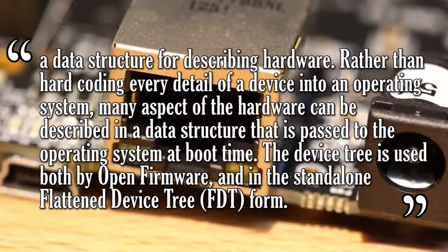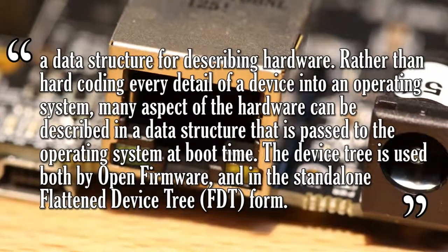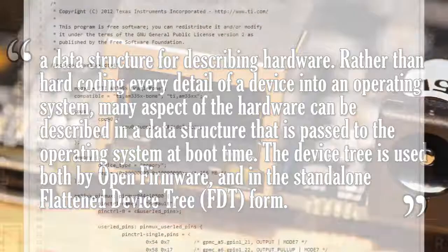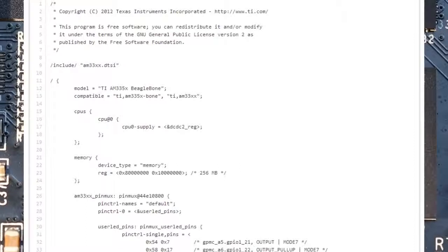The device tree is used both by open firmware and in the standalone flattened device tree FDT form. This is what a device tree description of our Beaglebone Black looks like. It's a DTS format file.